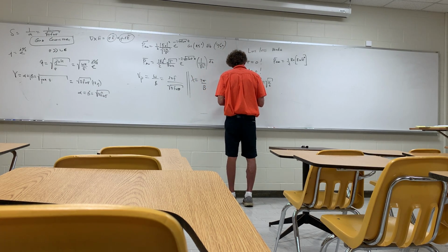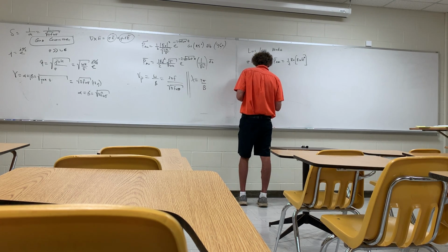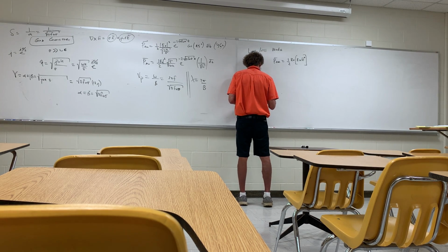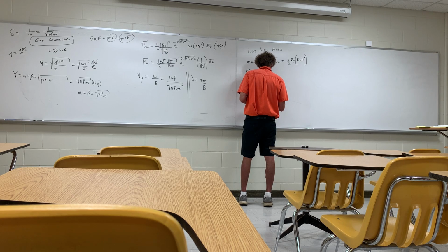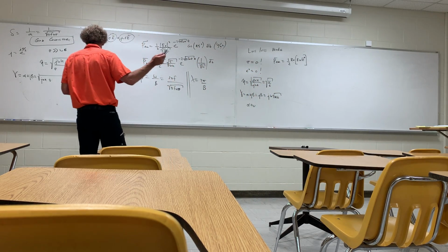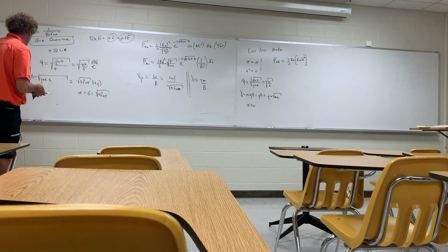And then when we talk about the propagation constant, which is alpha plus j beta, it's simply going to be j beta. Alpha will be 0, and that will be equal to simply j times omega square root of mu epsilon. Right? And you can see that from over here. Did I erase that? Yes. No, I didn't.